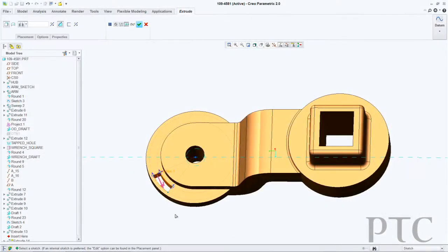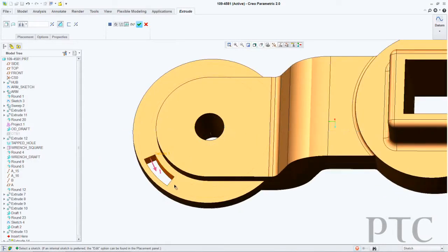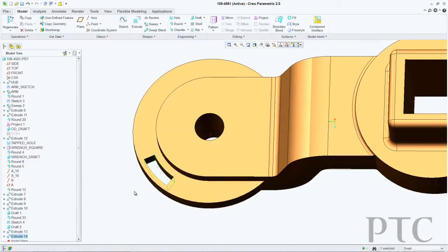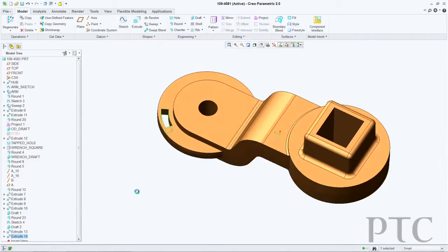a slanted rectangle. We've also enhanced the ability to automatically regenerate the model, or dynamically regenerate the model. Now I can simply click on a feature, and when I do that, it will show me the dimensions for that particular feature. Each of those dimensions will have drag handles on them. I can directly click on those drag handles and move them, and it will modify just that particular dimension of the section. And in real time, update the rest of my surrounding geometry for me.